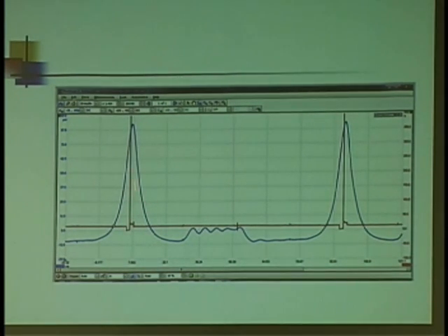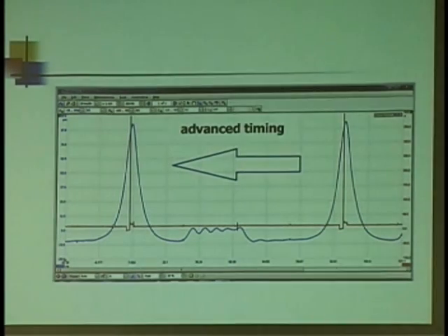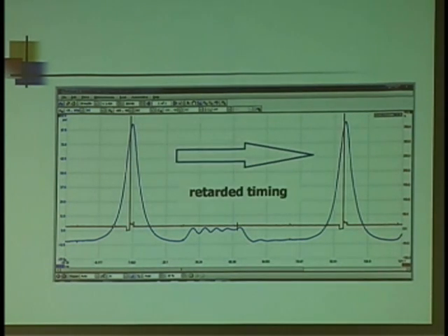So if I see that this ignition event occurs over to the left of that piston position, it's got to be advanced timing. That's what I'm going to be looking for. Conversely, if it's moving over to the right, past the peak, happened after TDC, it's retarded. And I can use those same references to the other lines that I lay out and show you here in a second.